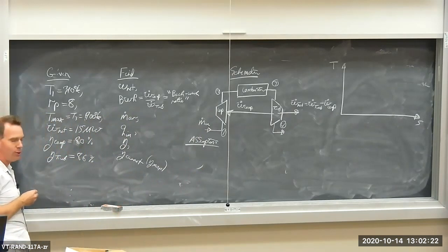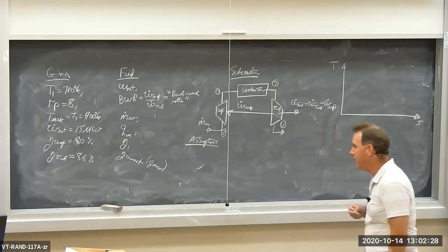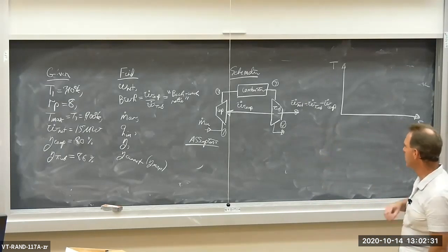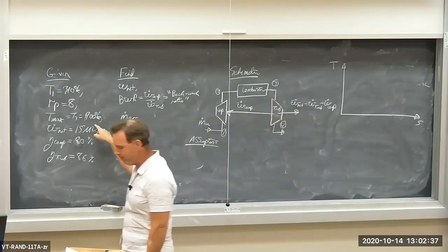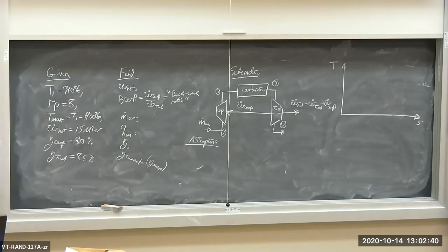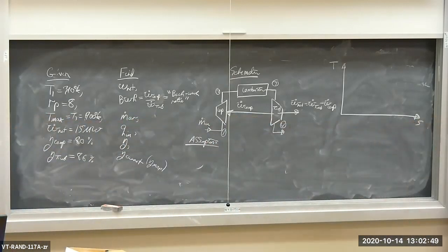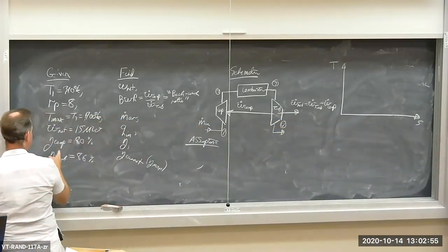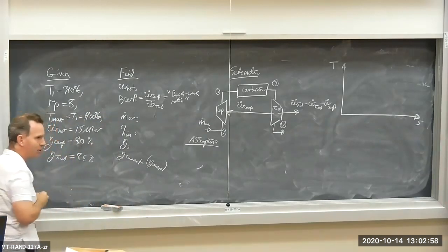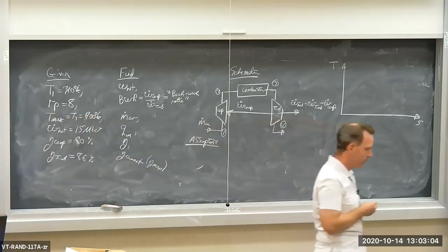So the compressor pressurizes the air by a factor of 8 in terms of the ratio of inlet to outlet pressure. The maximum temperature, presumably that occurs after the combustor, so that's T3. The maximum temperature is 900 degrees Kelvin. So we heat up the air by up to 900 degrees Kelvin. The net power produced by the gas turbine is 15 megawatts. And the isentropic efficiencies for the compressor and the turbine are 80 and 86% respectively. These are not isentropic turbines and compressors.